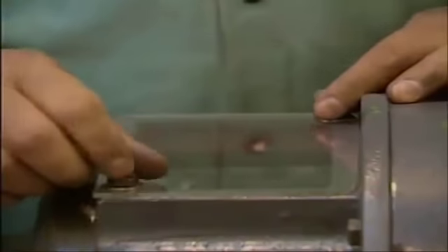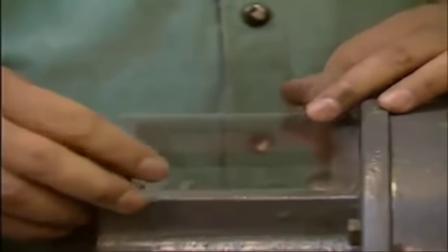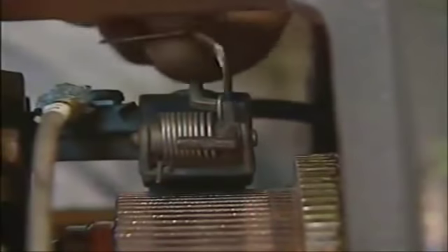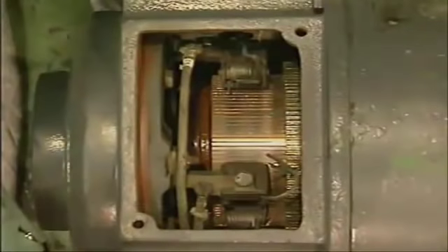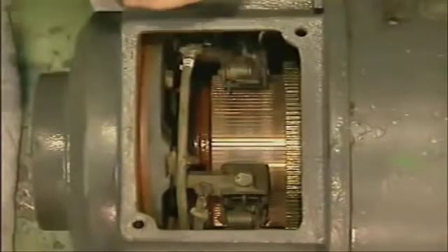The first step in disassembling a DC motor is to lift up or completely remove the inspection covers on the motor end bell to gain access to the brush rigging. Next, the pigtail bolts are loosened, and then the pigtails are slipped out of the bolts. The brush tensioning assemblies are then released, and the brushes are removed.